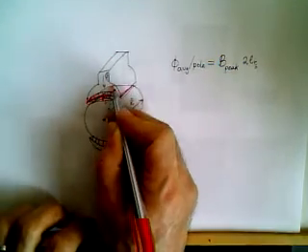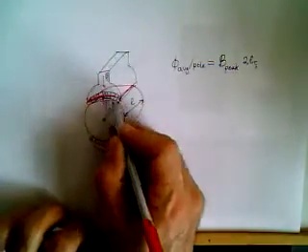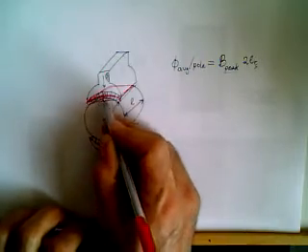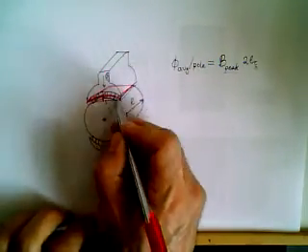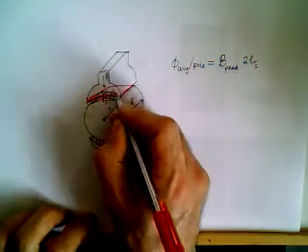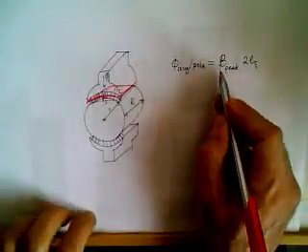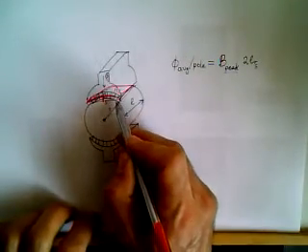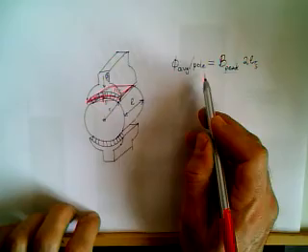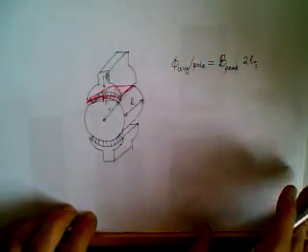So this is the rectangle. Although it's a little bit curved, we assume it's like a rectangle. So this portion and this portion create an area here, and this is multiplied with the flux density. So this is the average flux under the pole.